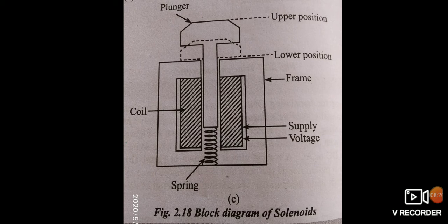The cutaway section shown in the figure illustrates the operation of a solenoid actuator. The spring return plunger is held in the upper position when the coil is electrically de-energized. When voltage is applied to the electrical coil, a magnetic field is produced in the solenoid frame. The frame is essentially permeable magnetic laminations excited by the coil. The plunger is actuated by the magnetic field, pulling it down against the spring pressure.